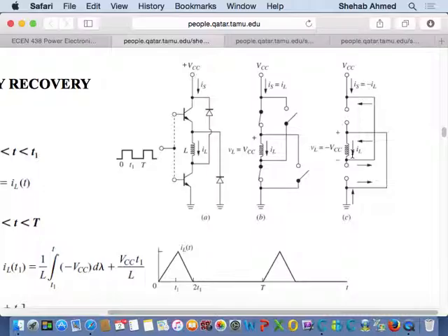So how is current passing through? It's already a complete circuit for the big source, right? The ideal source VCC. But you have current. I mean, you force current to the circuit. Inductors will force current to flow through a circuit. The inductors will force the diode to turn on.